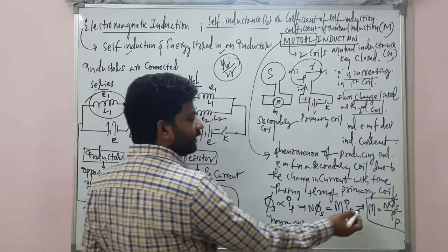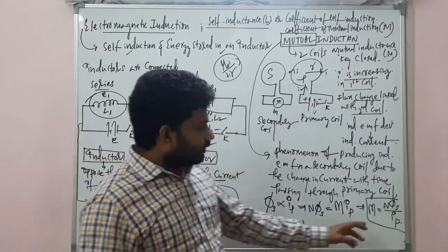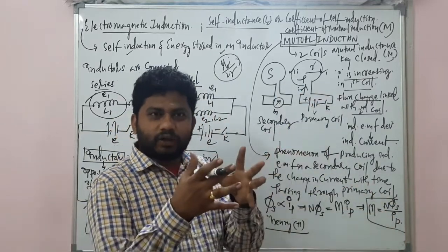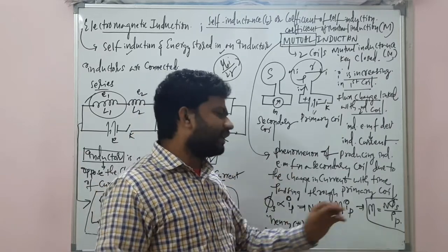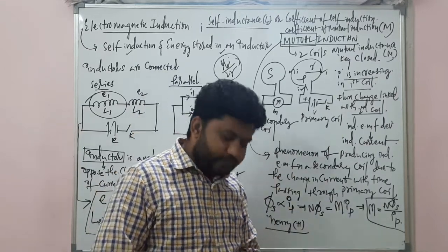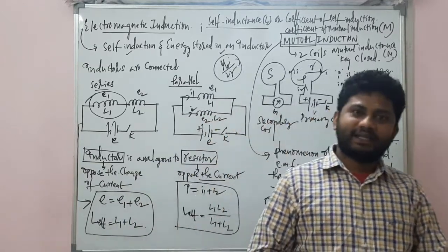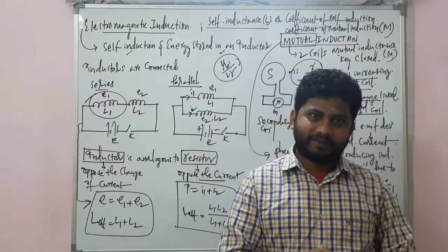And this mutual inductance depends on, as you can see, the geometry of the coil and the distance between the coils, the number of turns, right? On all these factors, the mutual inductance depends. And most importantly, mutual inductance also depends on the orientation of the coils.